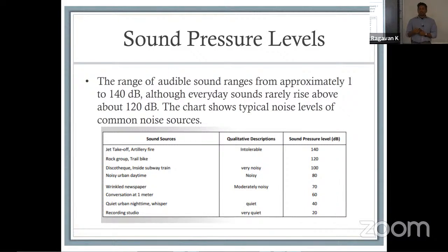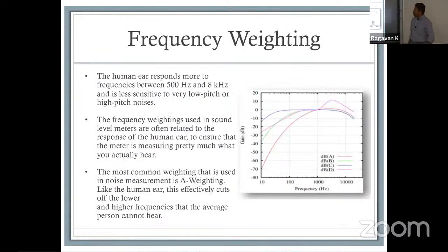The reason why oftentimes we get away with it is because, like I said, we are trying to optimize for a different variable, and acoustic noise being a side effect of that, we sometimes tend to ignore. The most sensitive frequency range is 500 hertz to 8 kilohertz. But normally, if I remember correctly, our audible range is 20 hertz to 20 kilohertz. That's the number we grew up hearing all our life. But the sensitive frequencies are between 500 hertz and 8 kilohertz.